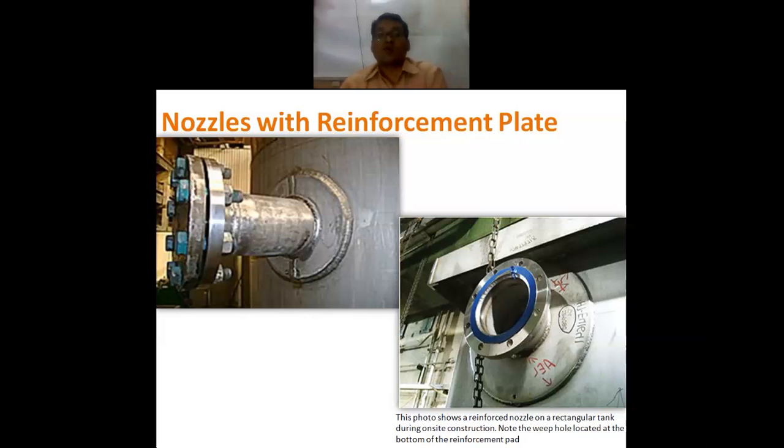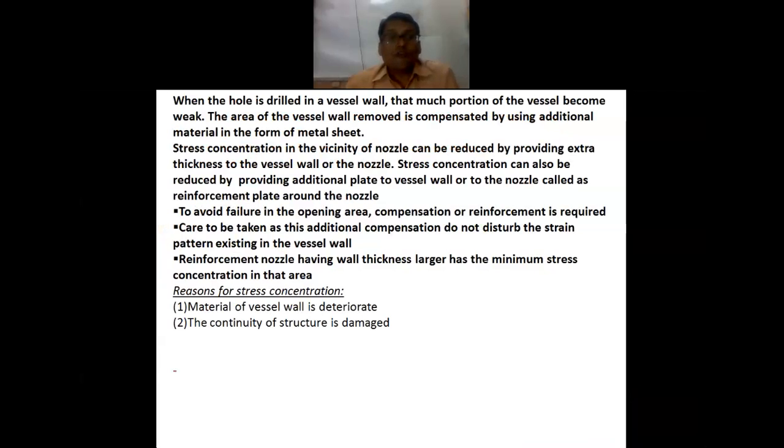Nozzles with the reinforcement plate. Now in these two figures, you can see the extra additional plate that is attached to the basic shell, and this is called a reinforcement. When a hole is drilled in a vessel, that portion of the vessel becomes weak.